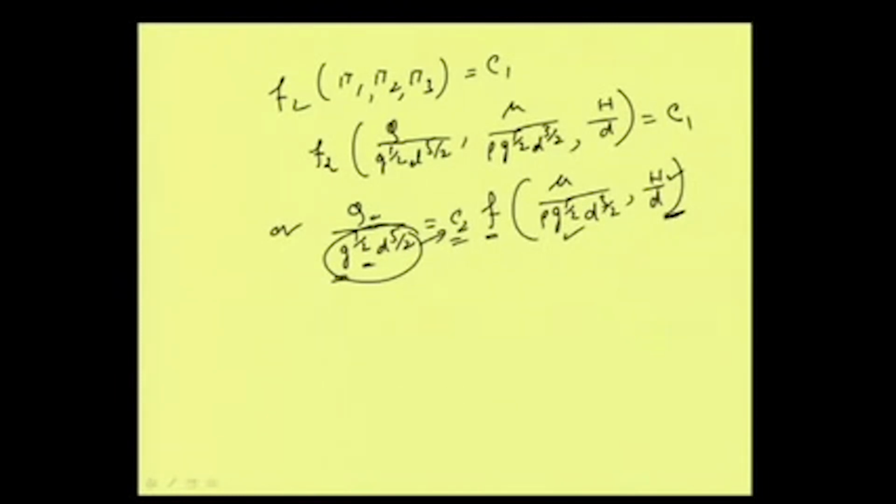Well, this expression we also got in the earlier method, Rayleigh's method, so this is fine. This expression is a little different, because earlier we got Q equal to A into root over twice g h. Velocity is root over twice g h, so area into velocity is what we are getting. Now, taking this part to that side, we can have it in this form. Let us verify whether this term and this term are identical or not.